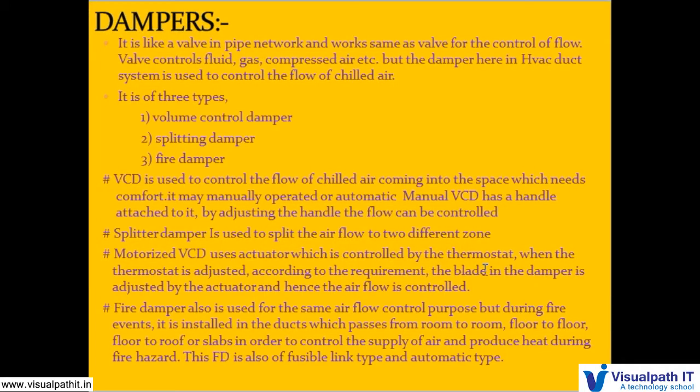The blade in the damper is adjusted by the actuator, and hence the airflow is controlled. Okay, this is up to the motorized VCD. Now the third one is the fire damper. Fire damper also is used for the same airflow control purpose, but during fire events.